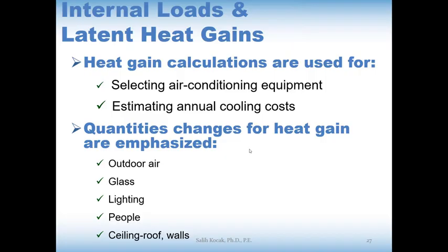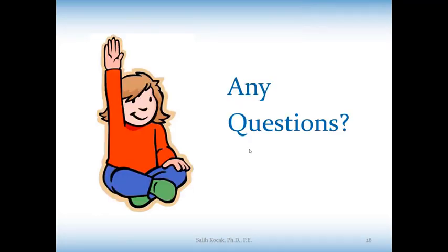After that, we just make our calculations. Finally, for any typical United States constructed building, the total heat gain should be around 15 to 60 BTUH per square foot of air conditioned floor area. This is important, it is like a self check. It is also under the tables, it's given to you. I will finish the class here with this slide, and please let me know if you have any questions.